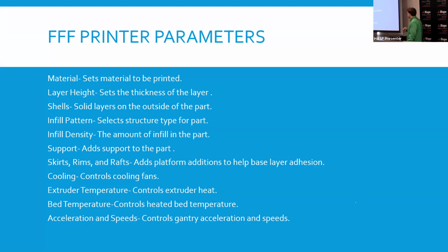Infill density, the amount of infill in the part. So how much are you actually going to put in the part? You can have 50% infill, so you're filling that hollow area 50%, or you can have, I don't know, 100% where it's fully filled. Usually the rule of thumb is 15%. That should give you good enough mechanical properties for a prototype. Support. Named as such, it gives support to the part.